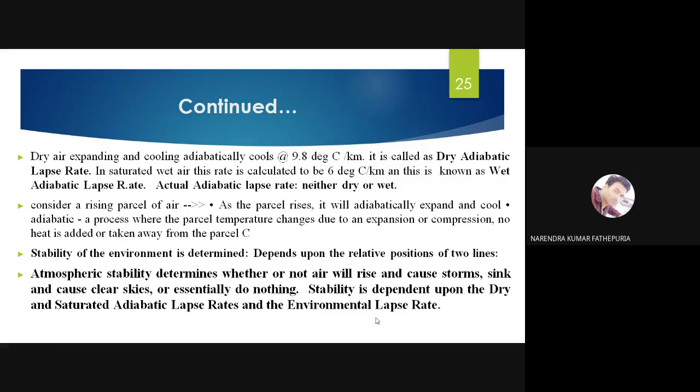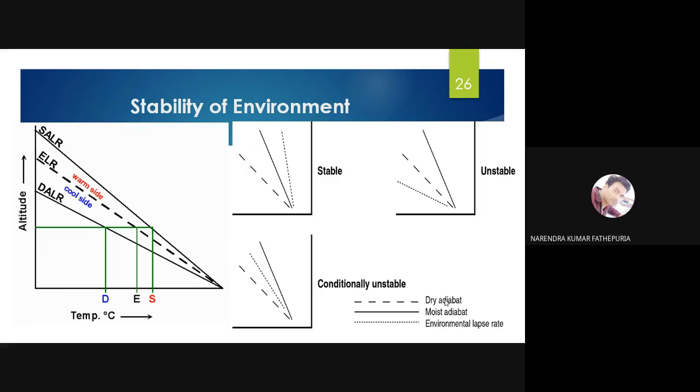So you are going to determine what will be the condition in the atmosphere, whether the atmosphere is stable, whether the atmosphere is suitable for pollution dispersion or not. If more dispersion and more dilution will be happening, then the pollutant will disperse quickly and easily, and the sky will be clear. Okay, if the dispersion is slow, if there is less dilution, it will take more time to take away the pollutant. So it is very important to understand the stability, and it depends on weather condition, temperature, as I told, wind speeds, pressure, everything. So this is the stability of the environment.